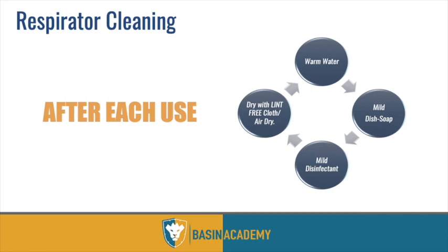It has to be a lint-free chamois because there are different chamois out there. That lint will get in there, get wet, get bacteria on it. Bacteria will grow, make a colony, you'll breathe it in, and the respirator will make you sick. Sorry for doubling that up, but it's true. So we want to make sure we keep it dry and free of any contaminant, including lint.